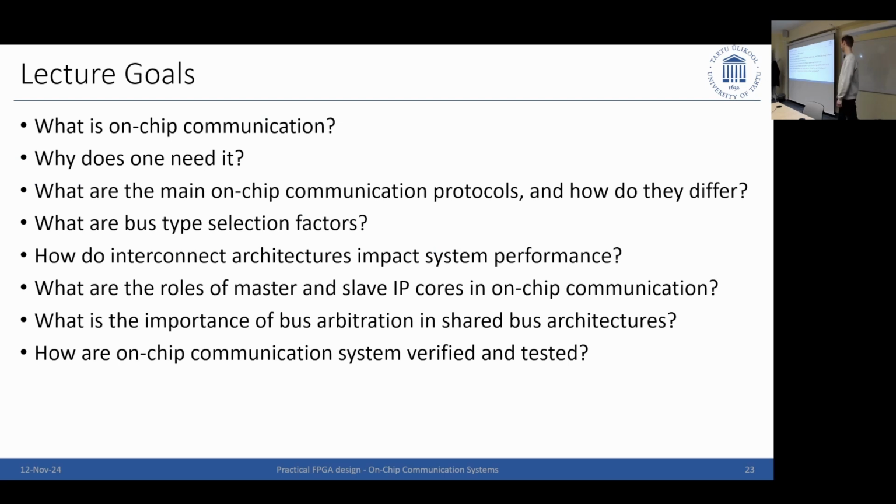I said not too long. So definitely we just covered here how it's tested and verified. Look into the standardized test benches, they exist. They should be used. You can of course write something on top of that, but every time you write your own test bench, you've got to verify that you didn't make a thought mistake. And if you write a bus system and the testing for it, that's going to be difficult.